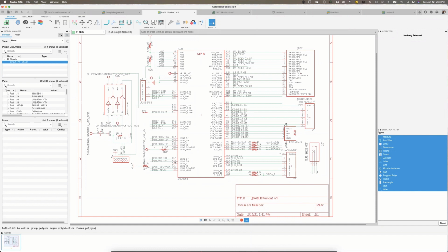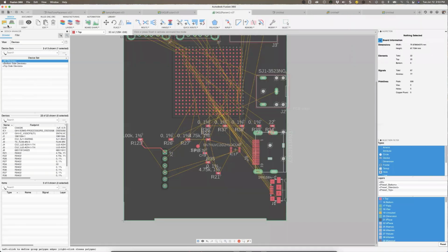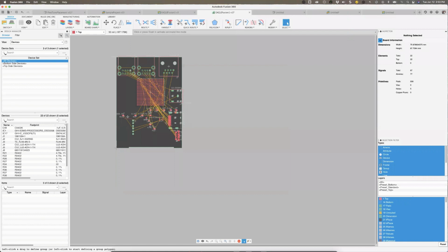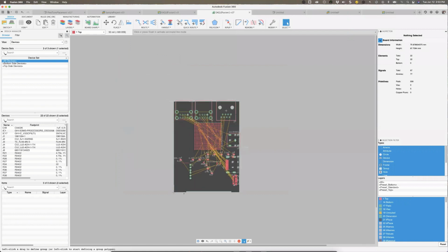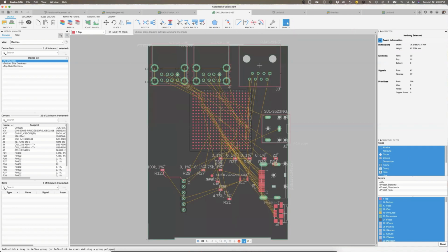Now, let's say I want to convert this over to my circuit board. I'm going to be selecting this icon right here, switch to PCB document. Okay. So I'll click here and this will create the board for me. It will use a board outline default. In this case, I just have this rectangle here. Okay. This is my PCB.